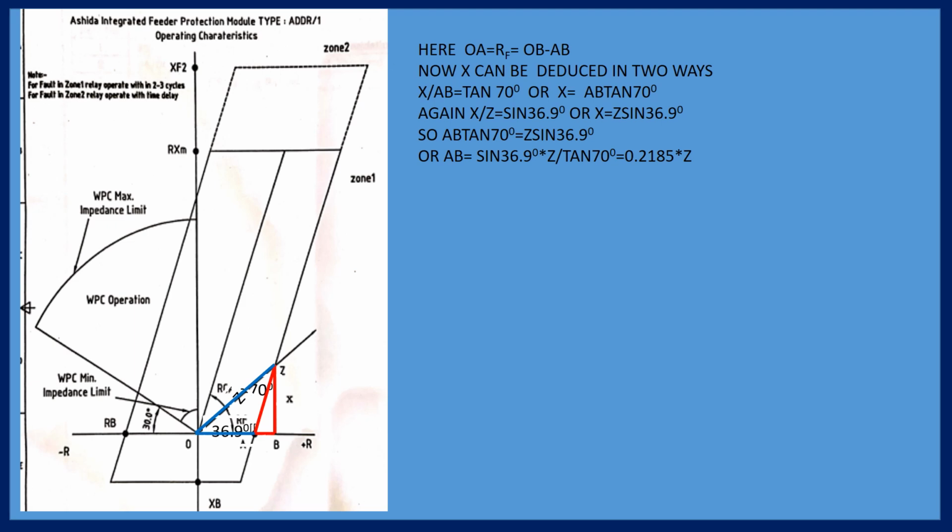So what is the facility of the earthing of the power transformer? It can create an earth fault during failure. If the OHE falls on the ground, or an insulator is broken, or any damage causes close contact with earth, then it will trip the circuit breaker. It is possible due to the earthing of one leg of the power transformer. So this is the facility of the earthing.